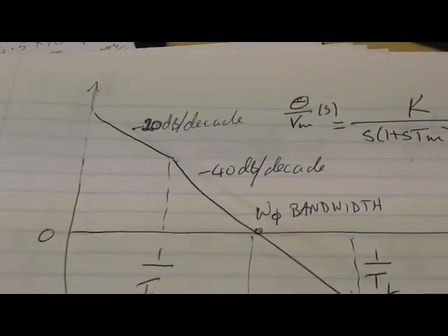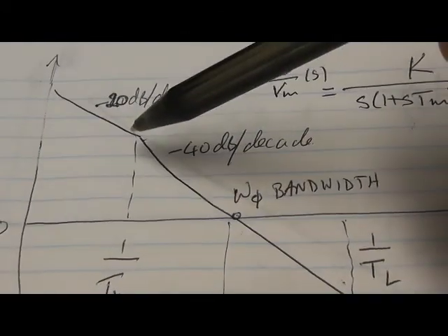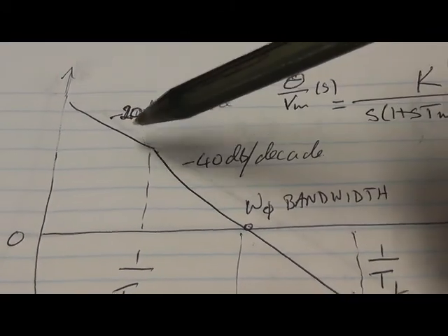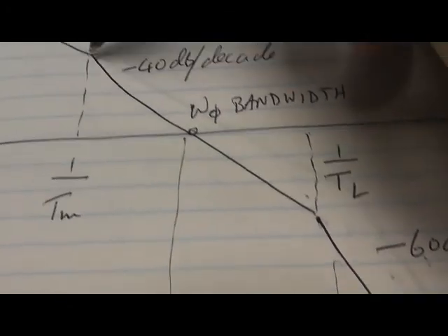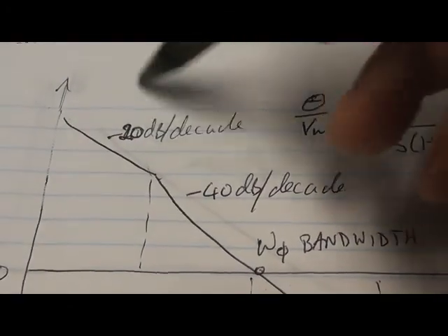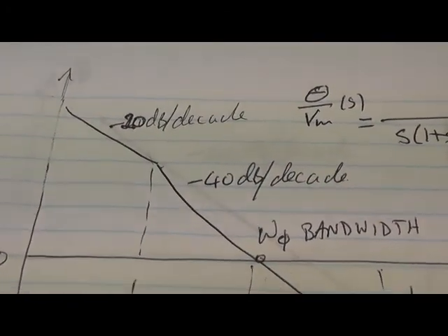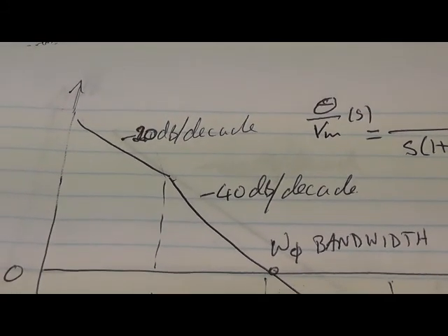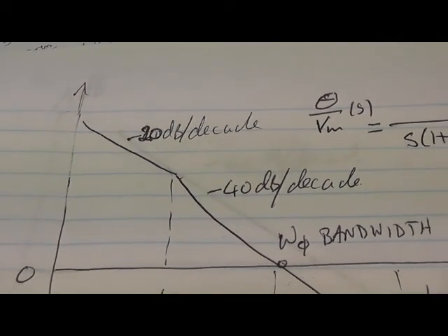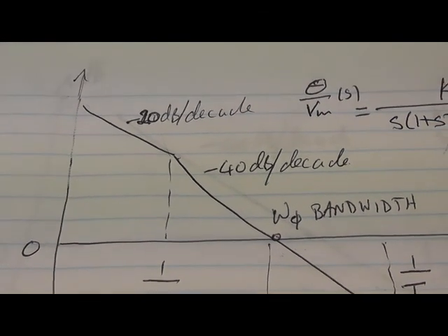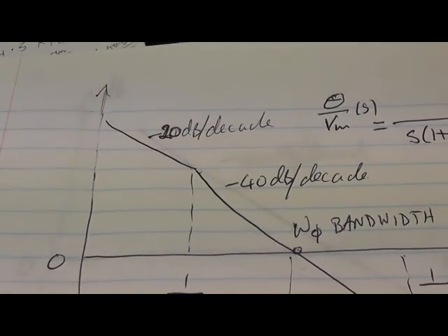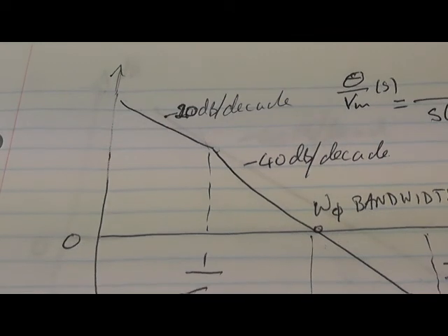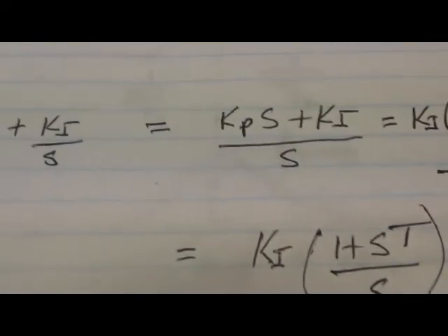Well, the first thing we do, it's probably just good practice, is we've only got one integrator here. It's probably a good idea to have two integrators at low frequencies, and that gives us quite a high gain at low frequencies, and that gives us more disturbance rejection, better tracking ability, and so on. And the motor will feel tighter when you actually try and move it as well. So in order to do that, we use this kind of PI compensator.